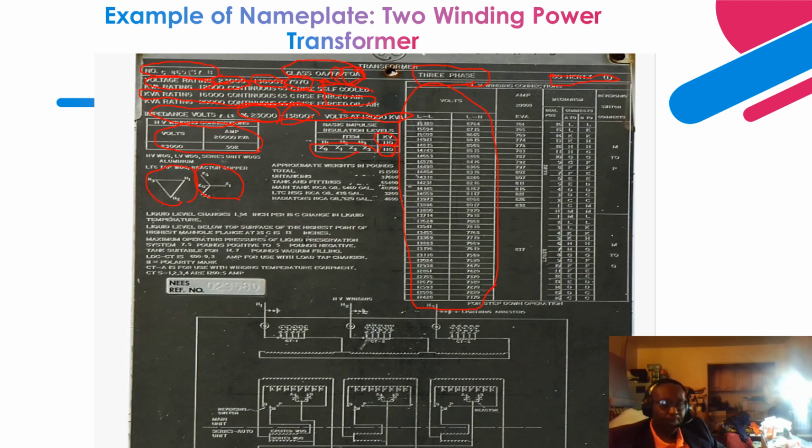is in operation. The difference between on-load tap changer and de-energized tap changer is that the de-energized tap changer is located on the high voltage side. The transformer has to be de-energized and isolated before you can change the de-energized tap changer. The de-energized tap changer varies the voltages on the high voltage side, and the on-load tap changer varies the output voltages on the low voltage side.